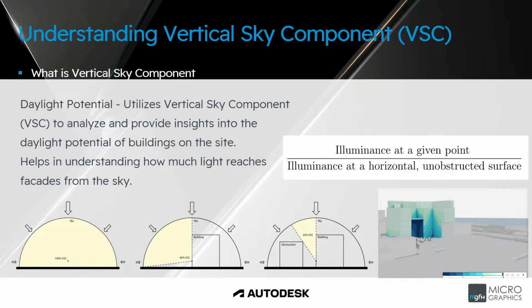Understanding vertical sky component. What is the VSC definition? By definition, the daylight potential analysis output is a sky component, a measure of how much light reaches the facades from the sky, shown as a percentage score. For different points on the building, the sky component score indicates how much light would shine through a window placed at those points. For the usual use case of daylight and vertical facades, sky component is referred to as the